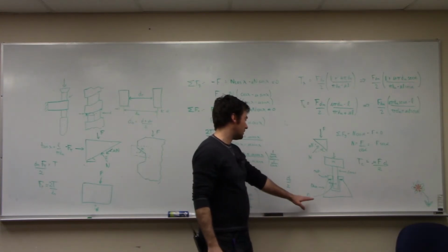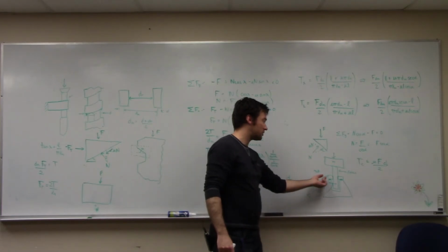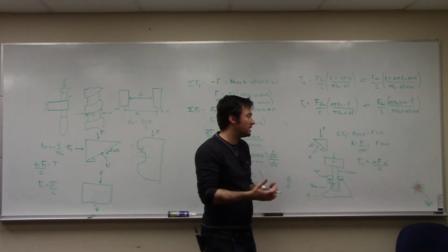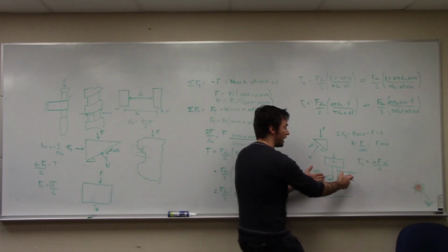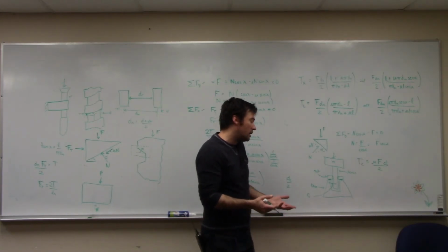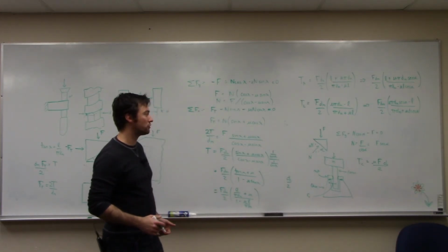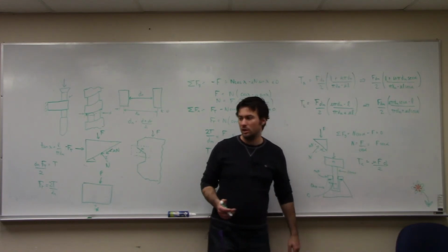The only thing that you need to keep in mind is that this is actually a pressure. It's acting over some area. So sometimes determining what effective diameter of the collar to use, it's probably not the outer diameter of the nut in this case or the inner diameter of the nut. We're going to put it halfway in between, kind of like we did a mean diameter for the screw. We kind of have a mean collar diameter that we're going to be interested in.